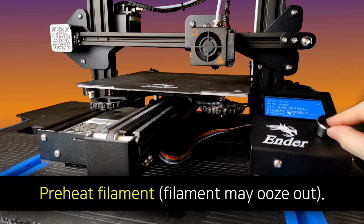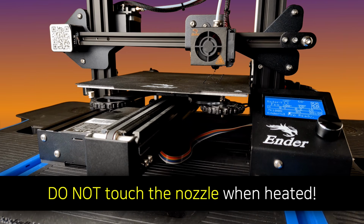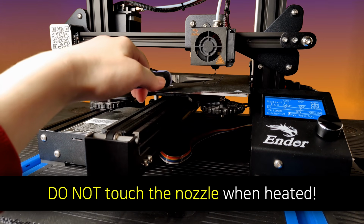PLA plastic is a common printer filament. If you're using a different material such as ABS plastic, then you'll need to preheat with a different temperature. If the printer has been used before, some filament will likely come out when preheating. This is why I moved the nozzle up so that it's easier to grab the filament that oozed out. With that being said, do not touch the nozzle, it is very hot.